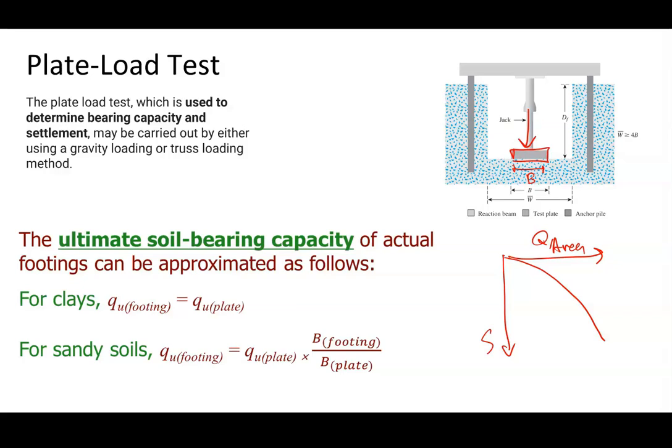Then when we have the results, QU of plate and settlement of plate, we can use formulas to find QU of footing, the actual footing, and settlement of footing.